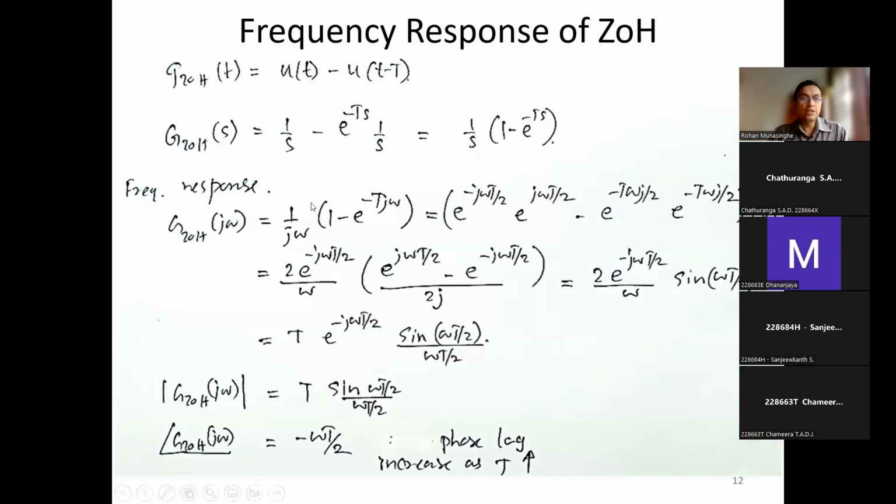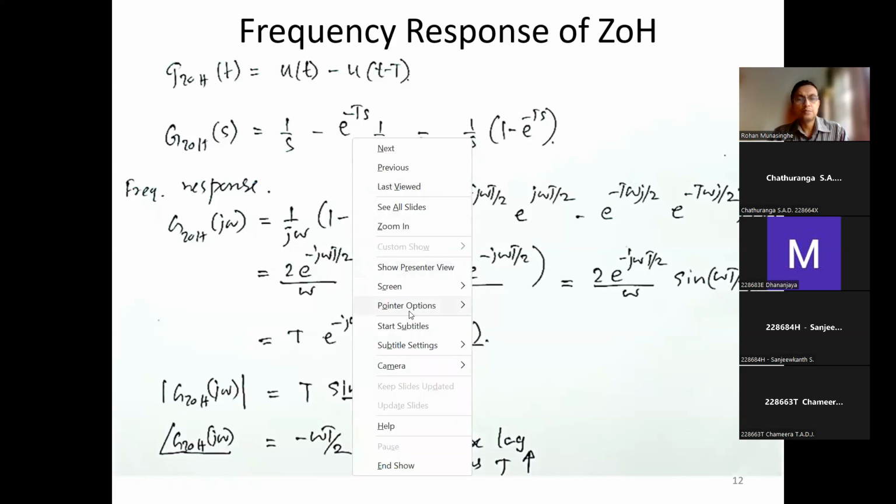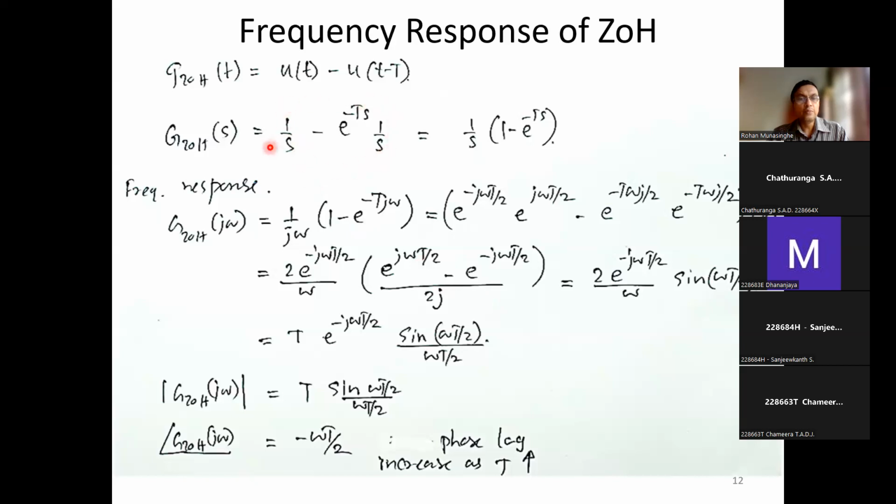So this is the continuous time representation of the pulse response, right? Continuous time pulse response. You write it that way, right? Now for frequency analysis, we don't need to go to the Z domain because the frequency analysis is entirely done in the Laplace domain, right? So this is not a discussion with the Z transform, but Laplace. So we simply get the, because we want to get the transfer function, we need to use this one, the zero order hold equivalent. Sorry, the zero order hold plant model, right? Or the transfer function of the zero order hold.